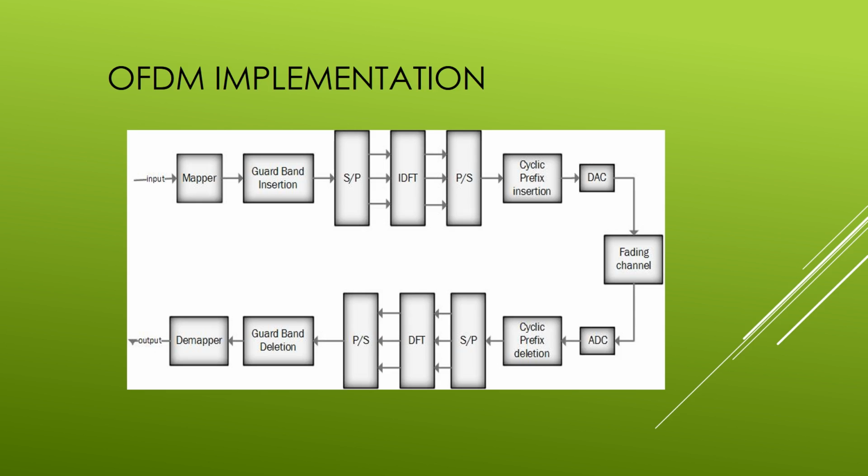This figure shows you the baseband module of the OFDM systems. The input data will first be modulated. The modulation method could be various, such as QAM and PSK constellation. Then the data will be parallelized to be the input of N-point IDFT, the inverse discrete Fourier transformation, which will transform the data in the frequency domain to the time domain.